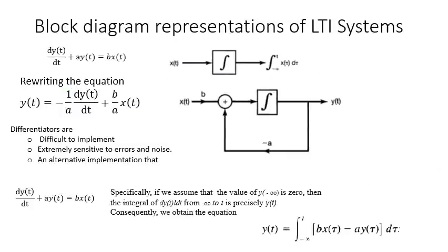So although we have solved this using the block diagram representation, differentiators have some problems. They are difficult to implement, and they are extremely sensitive to errors and noise, because a small variation will result in a big variation if we take the derivative. So an alternate representation will be using the integration.